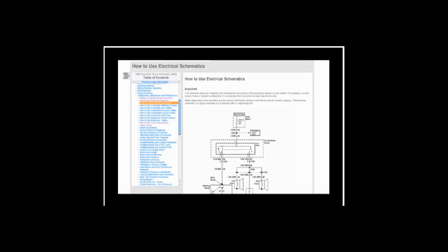Once again, at the top, at the fuse box, where's the voltage coming from? It's coming out of the fuse, the 20 amp fuse, going into the convenience center in this case, going off in parallel to both the windings and the latch side of the relay, and to the horn button to basically energize the relay, and then to the horn circuit. Once that winding reference has been met, the latch circuit closes and the horns will sound.